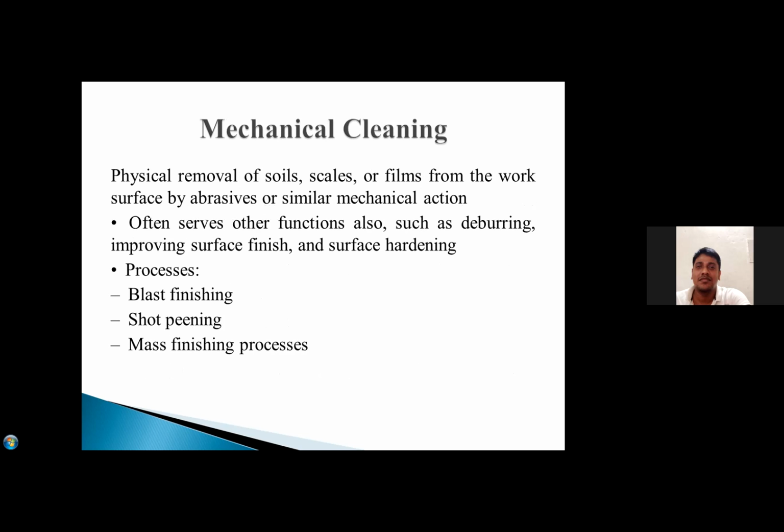Now, mechanical cleaning. Mechanical cleaning has basically three types: blast finishing, shot peening, and mass finishing process. Physical removal of soils, scales, or films from the work surface by abrasive or similar mechanical action often serves other functions also, such as deburring, improving surface finish, and surface hardening.